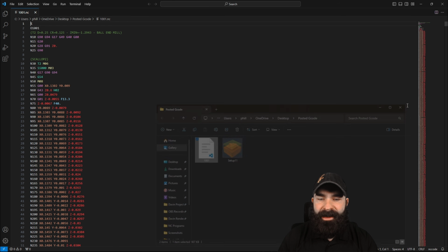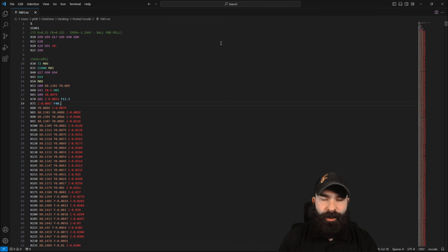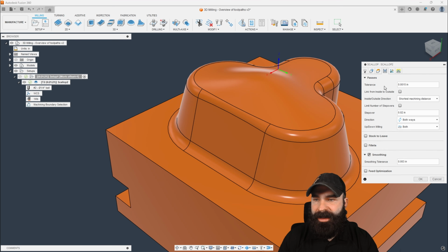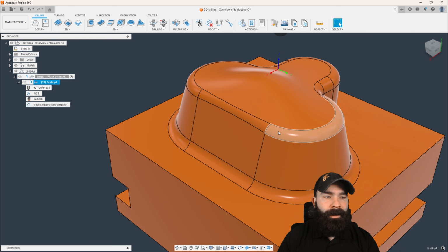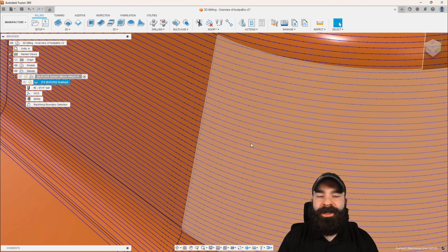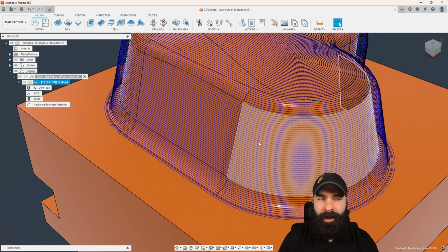So again, if I go back to everything that we're doing, and we adjust that one more time, let's double it up and see if we can get a change here in the window. So let's go up to 6. And again, now we're under 1 meg. So we are seeing that change. So we are slowly reducing points by increasing that smoothing tolerance to be able to go in and trigger a much cleaner profile without actually creating straight lines that should be arcs.